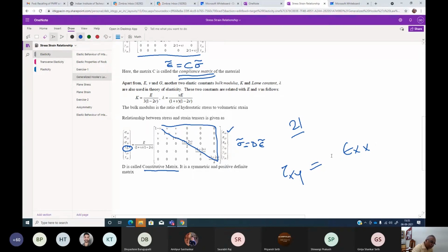So there is no relationship here. It is 0. Okay, that is the parameter 0. They are saying there is no relation. So, is it true for all cases? Absolutely not. This is for isotropic elasticity. It is true. But if you go to anisotropic elasticity, it is not true. There will be some value. That means shear stress in the xy plane will depend on the normal strain in the x direction. Actually all should be non-zero, but this is a very special case.